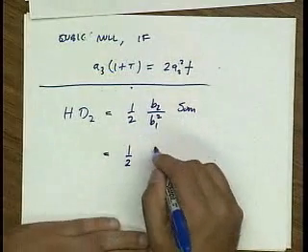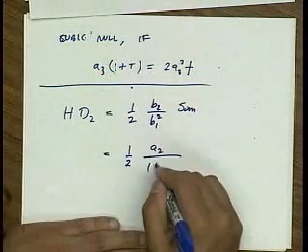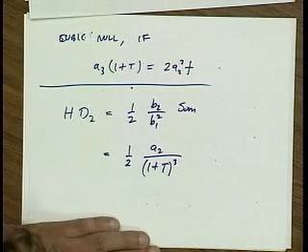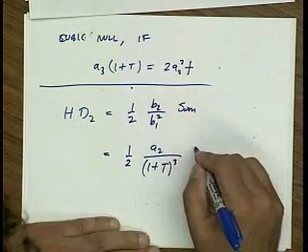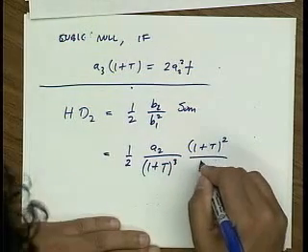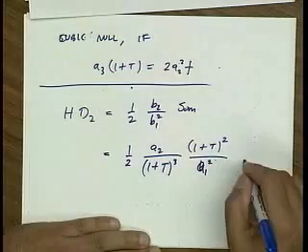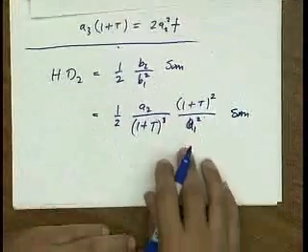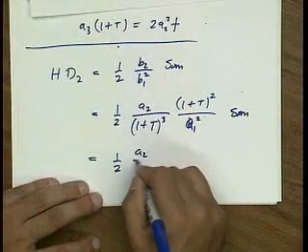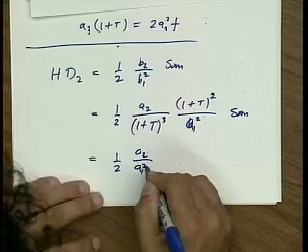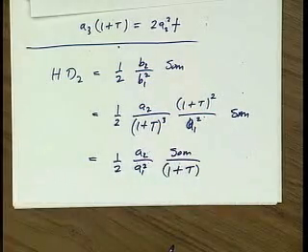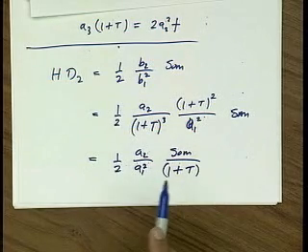So if I substitute, b2 I found is basically a2 reduced by the cube of 1 plus t, and b1, of course, is just reduced by 1 plus t. And so when all is said and done, I have that the distortion output referred is reduced by 1 plus t. Now, why is it very important to look at the output referred?